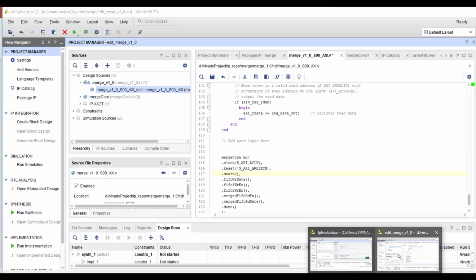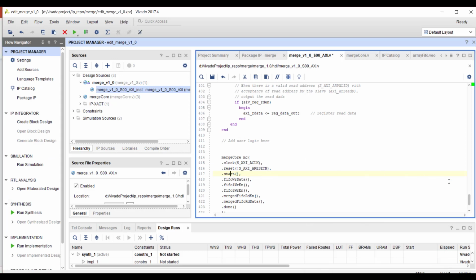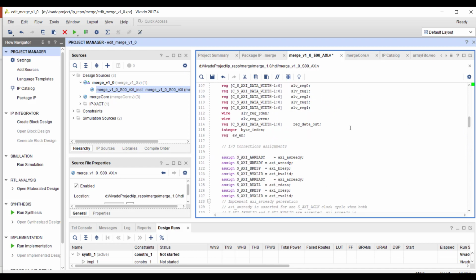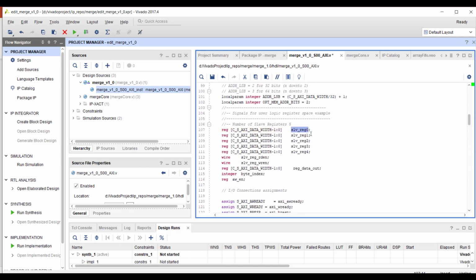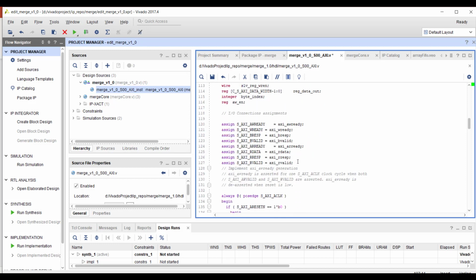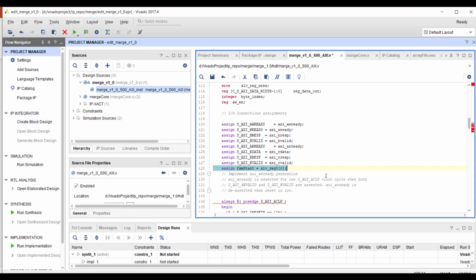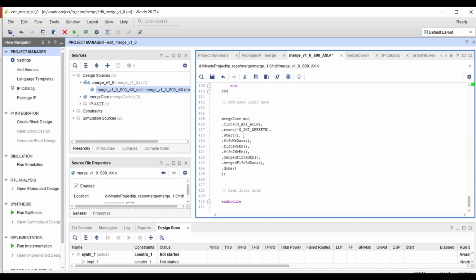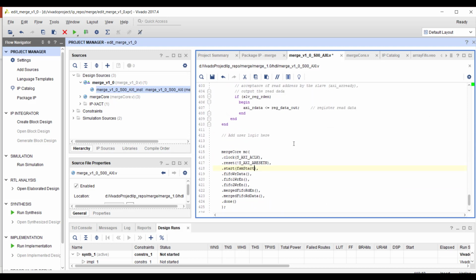Okay, so what should happen is when the processor writes to address 0, which is our slave reg 0, the bit 0 will be connected here. So I will take the slave reg 0 and I will assign something like FSM start equal to 0th bit of this register, and this FSM start I will declare it as a wire, and I will connect that signal here.